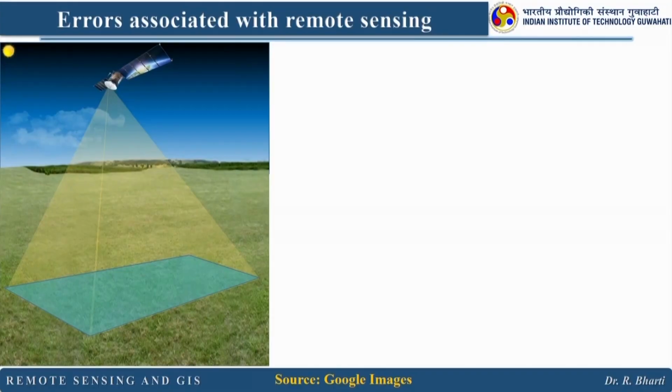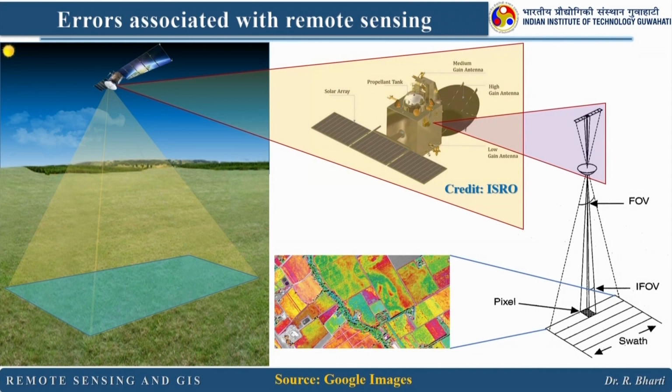Here you can see a satellite active in this area and images have been generated. So, here you can see we have a source. In passive remote sensing, the sun is acting as a source of energy and this is illuminating our surface, and a satellite is active in this particular area. So, the satellite is receiving such signals and it is generating this particular image, right. Now, what happens if the position of the sun is different, and what will be the effect on the acquired images?